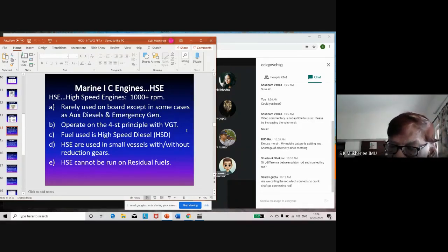Now, when the engine is delivering hot gases to the turbine, if the nozzle through which the hot gases are passing and are directed to the turbine blades can be narrowed, then the flow of the exhaust gases becomes faster. If there is a faster flow of gases through those narrowed nozzles, then the turbine gets a bigger torque to rotate at a faster speed.